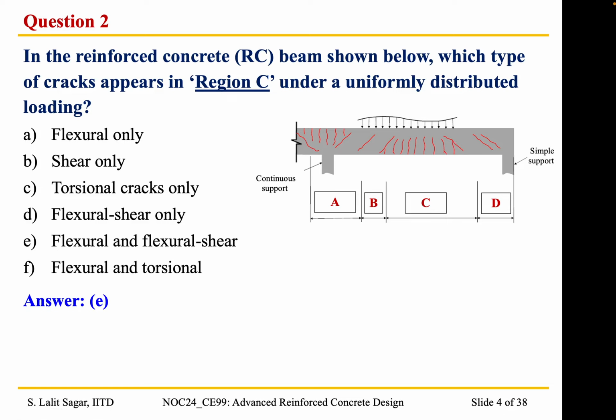they initially develop as a shear crack, but later on, because of the extension of the flexural cracks, they tend to become flexural shear cracks. So option E is the right answer. Okay, moving on.